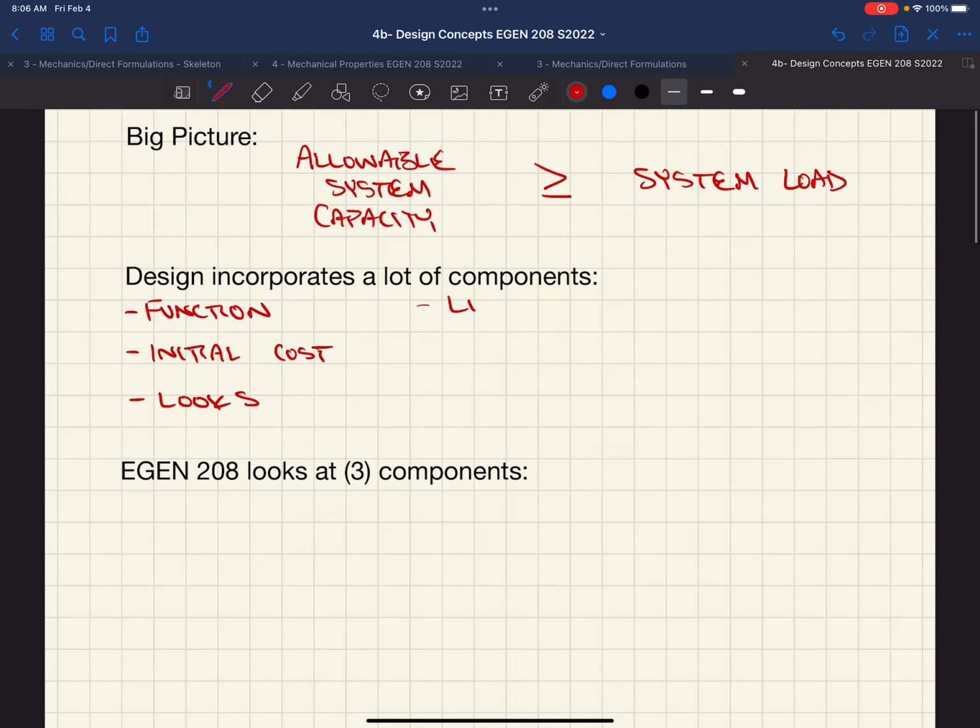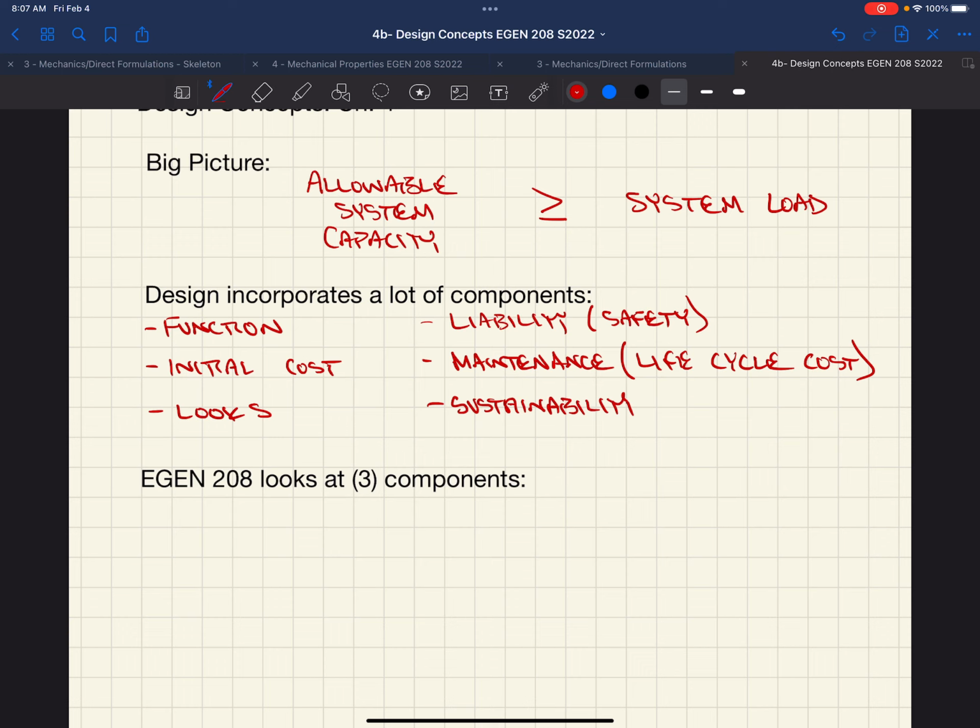For you CETs out there, you'll learn about, if you haven't already, LEED certification with the Green Building Council. All new buildings on campus have to meet one of the tiered approaches for essentially sustainable design. They limit how far away from the job site you can procure materials. You get dinged if you are transporting something from, say, New York to build something in Bozeman.